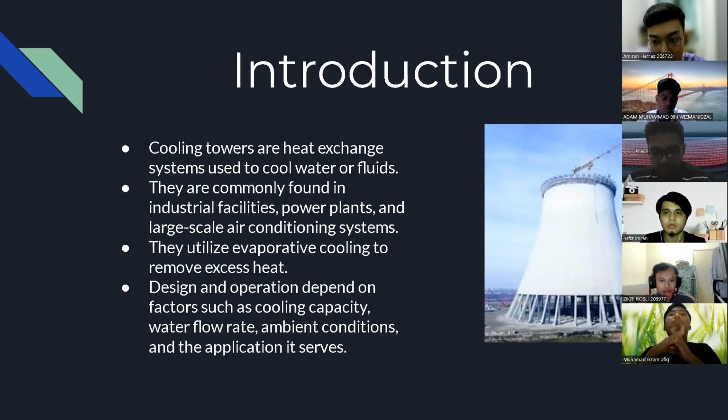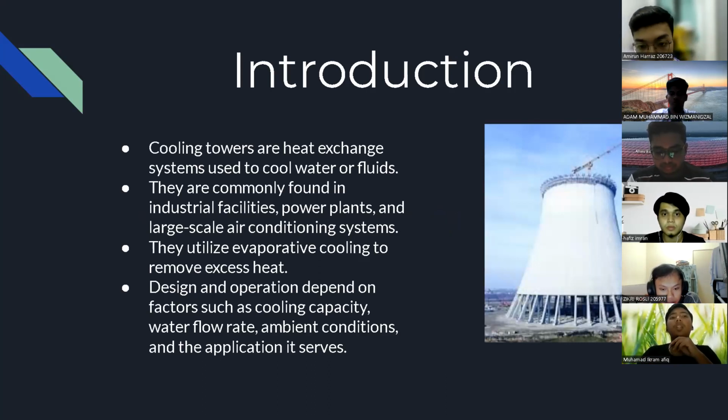So, what is cooling tower? So, the cooling tower are heat exchanger system used to cool water or fluid. They are commonly found in industry facility, power plant, and large-scale air conditioning system. They utilize evaporative cooling to remove excess heat. The design and the operation depend on factors such as cooling capacity, water flow rate, ambient condition, and the application itself. So next slide.